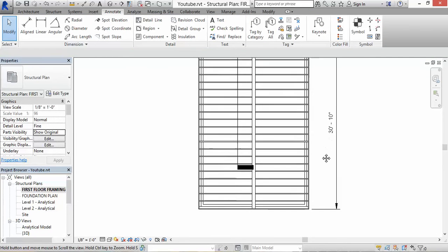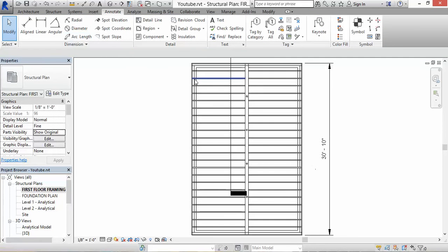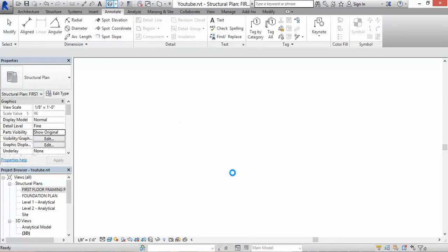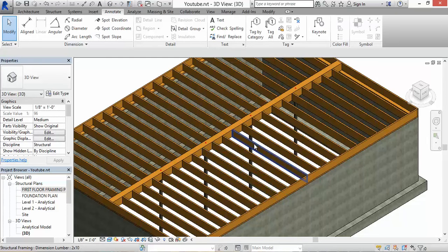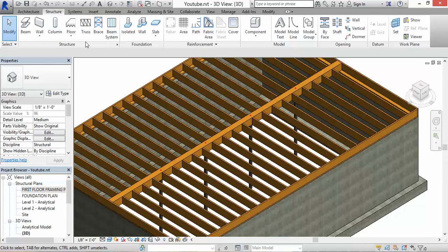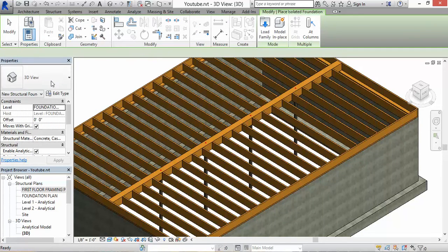Pretty close. So right here, we have our joist, we have our girder, and we have the Lally column supporting the girder. I could also put, you know what? I'll do this real quick. You could put in footings on those Lally columns. It's kind of hard to see, but go where it says structure, go where it says isolated, click on it.